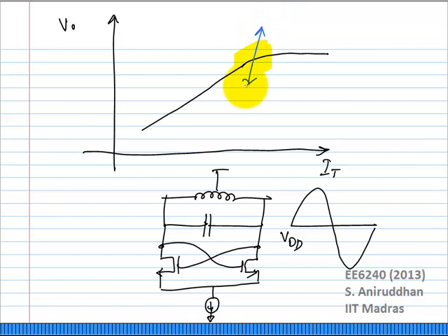Right? For the VCO, I always want to operate in the knee region. Okay? This curve I have drawn is output amplitude versus IT. For a given IT, I can draw output amplitude versus RP. And I'll have to choose RP such that I am at the knee region of the VCO. Understood? Okay?